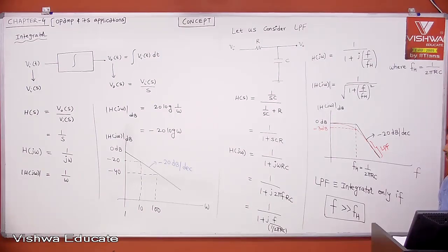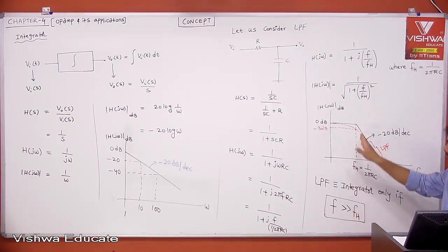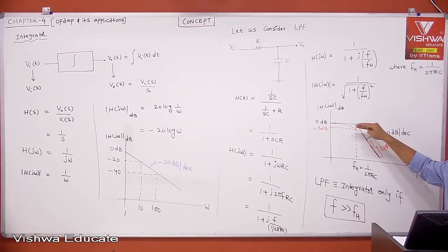What is a low pass filter? It passes low frequency signals, then after some frequency, it attenuates the signal significantly. Till the higher cutoff frequency, the attenuation will be 50% of the maximum output signal it can pass, with respect to power.